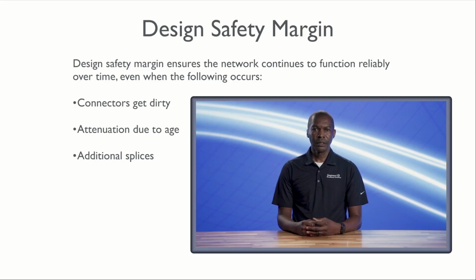Design safety margins ensure the network continues to function reliably over time, even when the following occurs: connectors get dirty, attenuation increases due to age of the cable, and any additional splices are needed. The recommended safety margin may be anywhere from 3 to 6 dB.